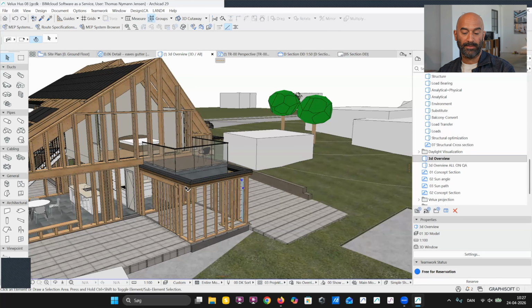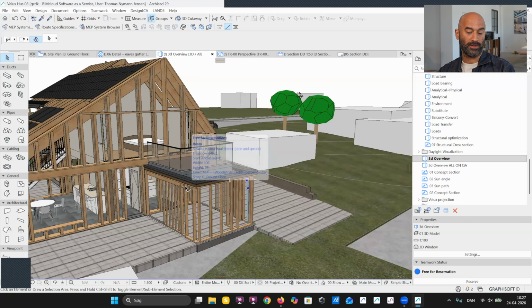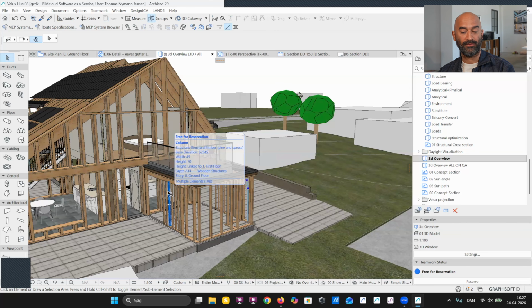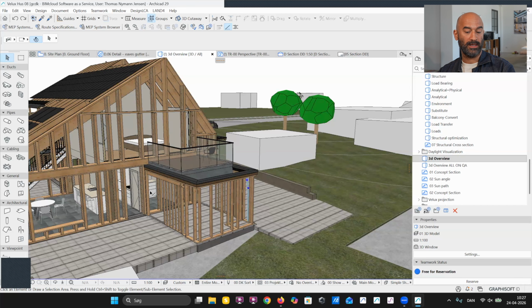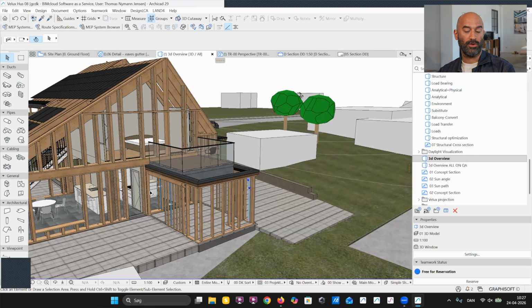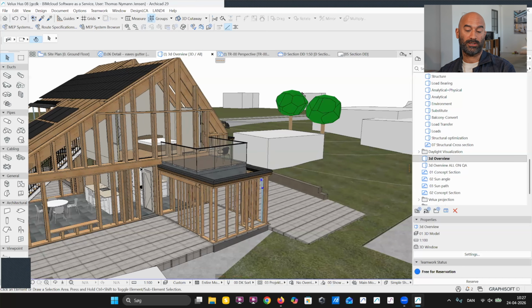And once I have a parametric 3D roof, which could be constructed by a composite just as well as my walls, so I can determine the thickness of the roof and the thickness layers of all the building materials inside the roof, I could actually go to my roof wizard and have the program construct the entire wooden structure automatically based on a few rules that I'll set up determining the sizes of the rafters and the pillars inside the roof. Clever. Yeah, so it can actually generate this wooden structure automatically.